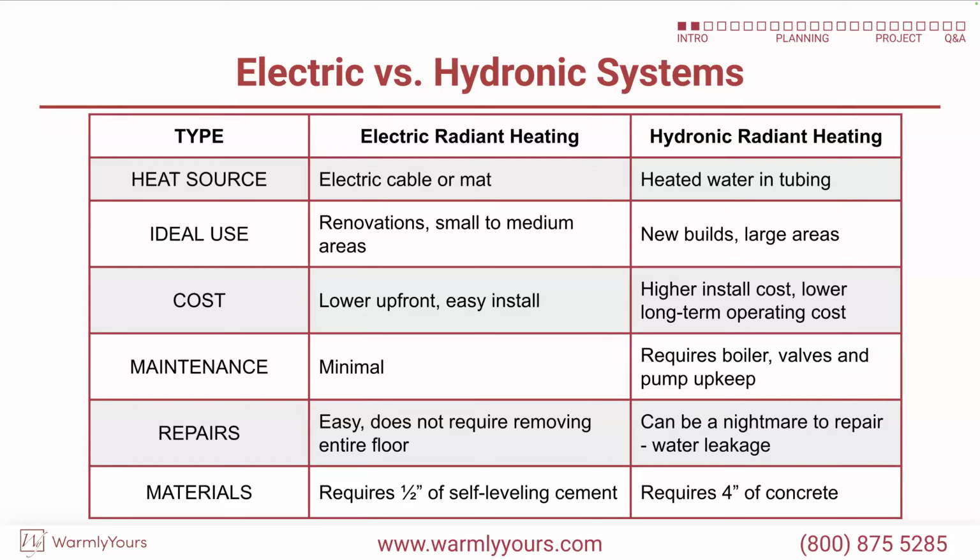And the reason why that's important, not only because 4 inches of concrete is going to cost a lot more than a half inch of self-leveling cement, but also if you have to do a repair, it's much easier to pull the LVT up, which you just pull apart, lift up, and go into a half inch of self-leveling, as opposed to getting into that 4 inch pour and getting a jackhammer and getting into that concrete. So it's much easier to do the repairs and that sort of thing.